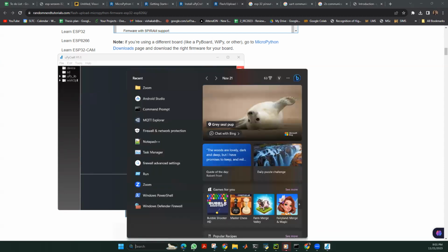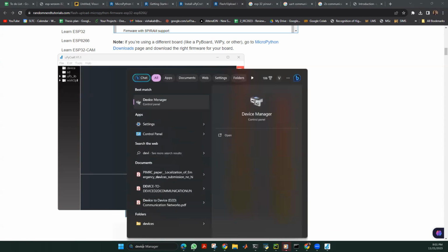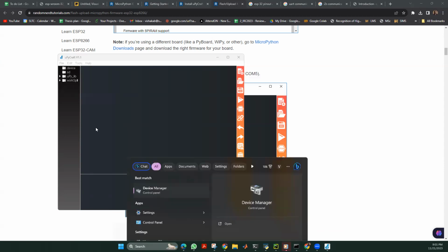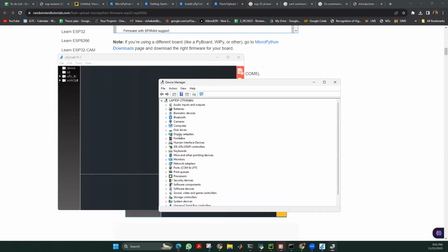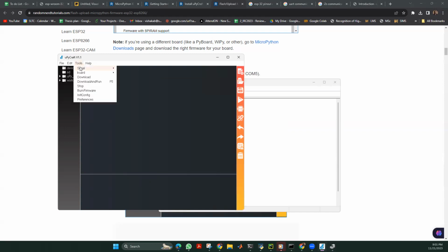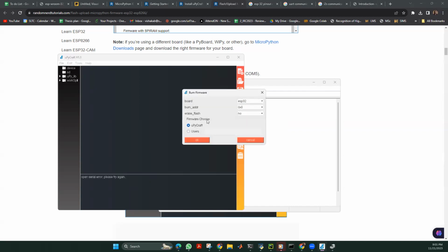In the device manager, you can see under ports the different ports that are already defined. In here, you can see it is mentioned that the COM5 port is already defined under the ports, which means that COM5 is recognized by the computer. So the COM5 serial port must be selected in order to do the communication.